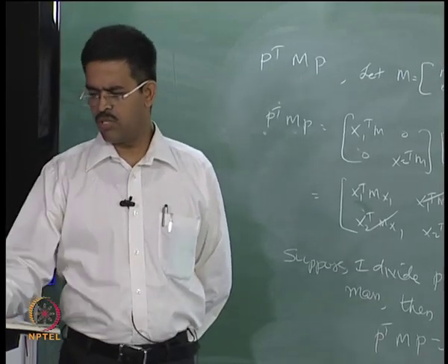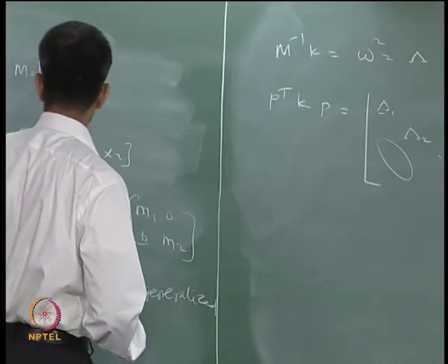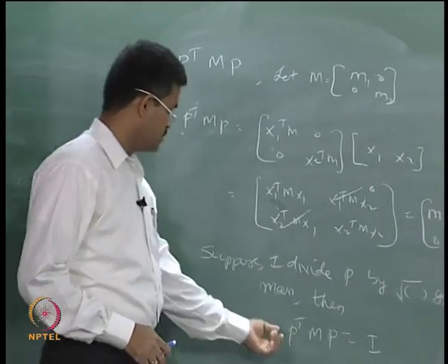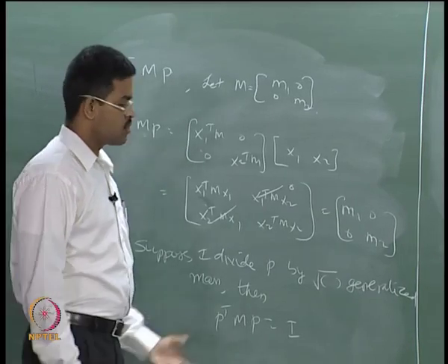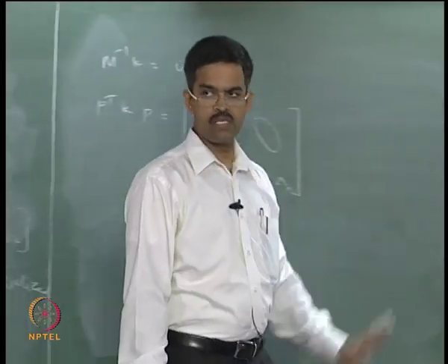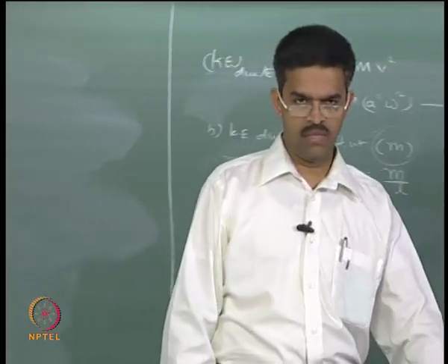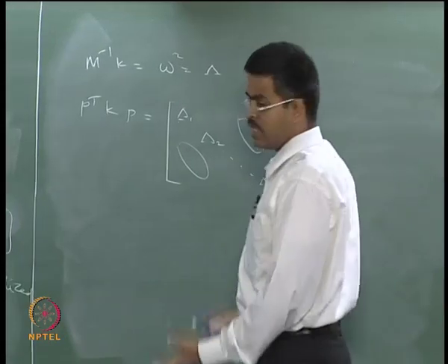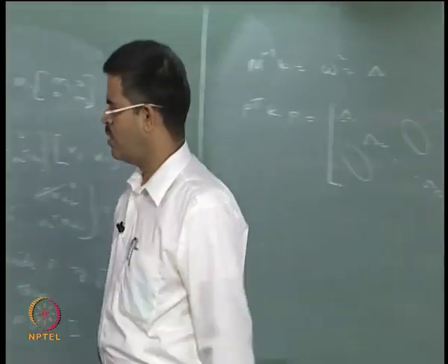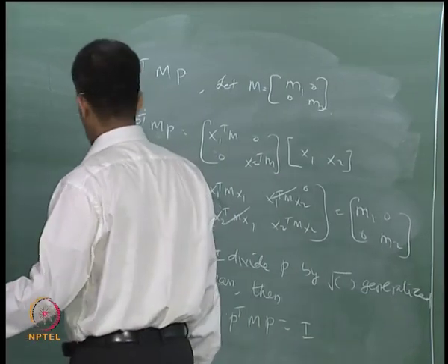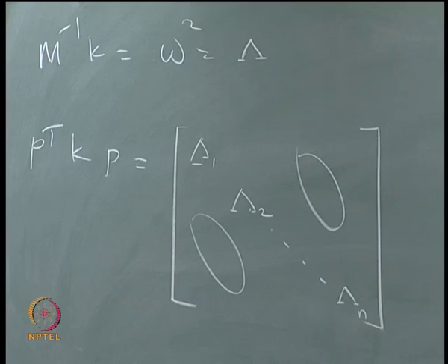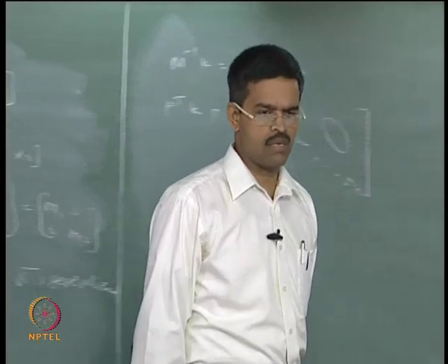So using these two concepts, let us see how I will use the weighted modal mass matrix for solving a multi-degree freedom system by decoupling the equations of motion. That is an advantage, because all these off diagonal terms get 0, I can decouple the equations of motion. I will show you how. I will take a very simple example, so quickly we can demonstrate that in a few minutes. Any questions here on the principle of orthogonality applied to mass and K matrices?